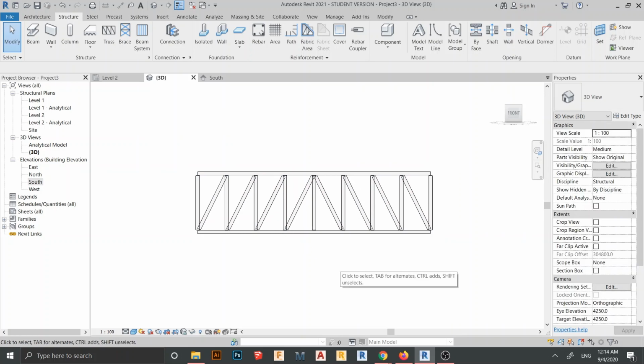And after we change here, the parameter will be automatic, same as in our family. When we want to create, let's say, a parametric kitchen or cabinet or wardrobe, it will work automatically, because we create parameters in our family here. This one is just a basic. Please take note, this one is just for beginner level, for those just starting to use truss in Revit. I gave quite a long example so that they can understand the point that I want to explain.